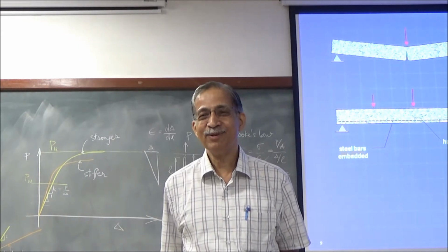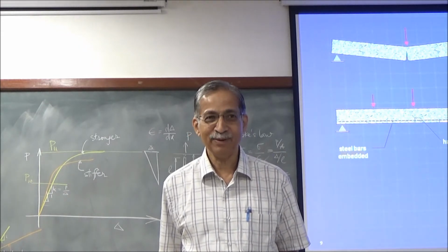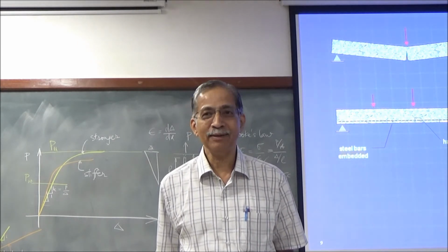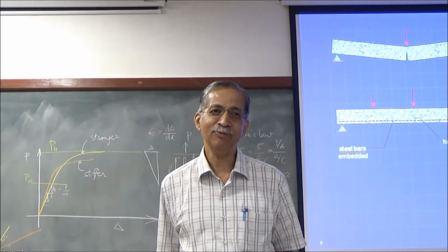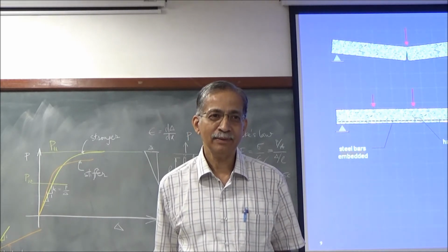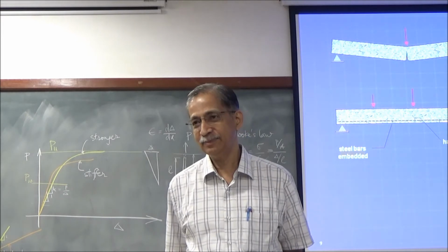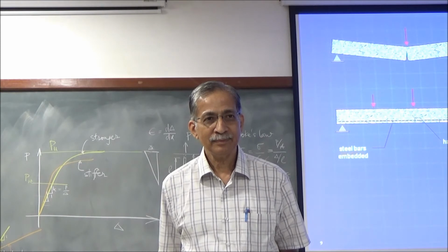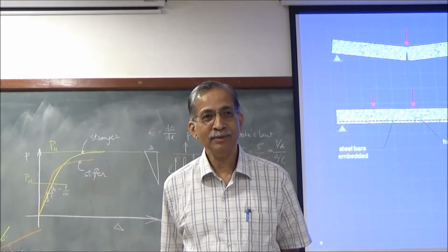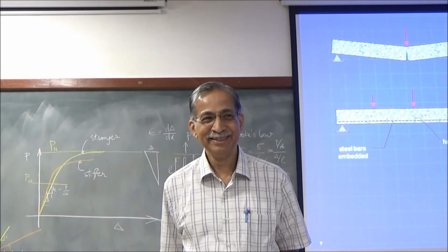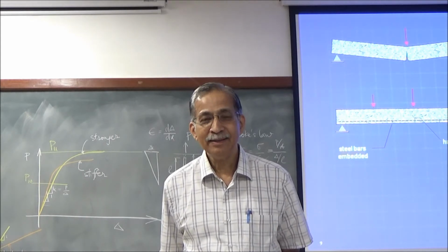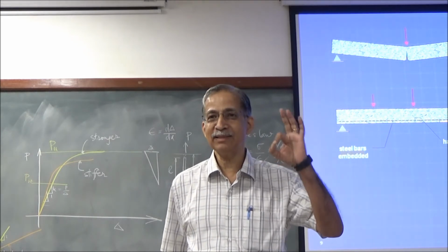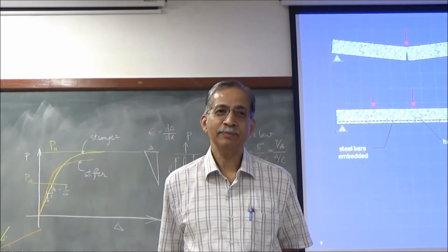No, you're talking about under-reinforced behavior. No. Ductility is very helpful under some kind of loading. What kind of loading? Earthquakes. How does it help? Steel might be undergoing... prolongs the damage. Slows the damage. Give me a correct answer. How does ductility help in earthquake resistant design? Energy will dissipate. Very good.